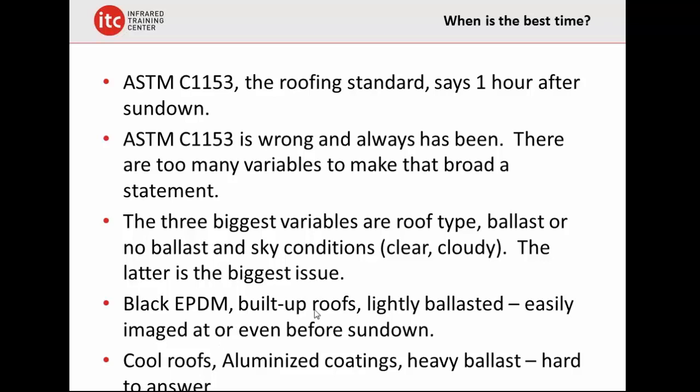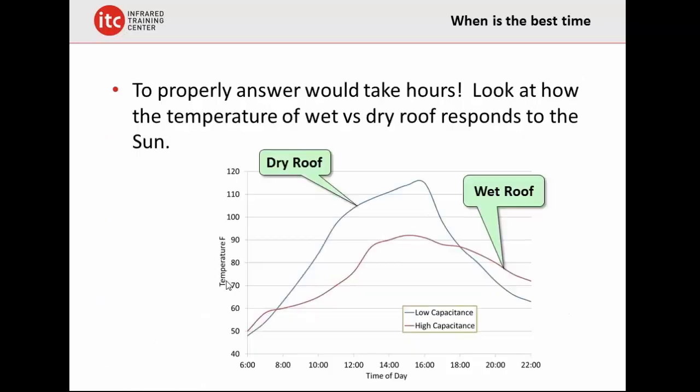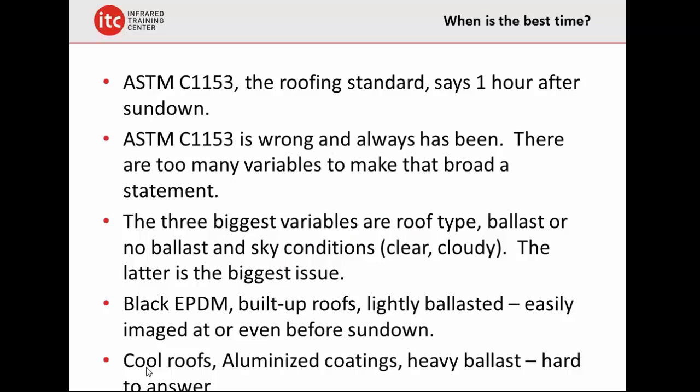The black EPDM, the built-up roofs, the lightly ballasted, they're easily imaged at or even before sundown. I've done surveys 2 hours before sundown when the sun was shining. It was great. We went up there to do a walk down on the roof, had our cameras, turned them on, and we saw thermal images because we had a nice clear sky. Okay, and the cool roofs, aluminized coatings, heavily ballasted, boy, that's hard to answer. So you just want to be careful with that.